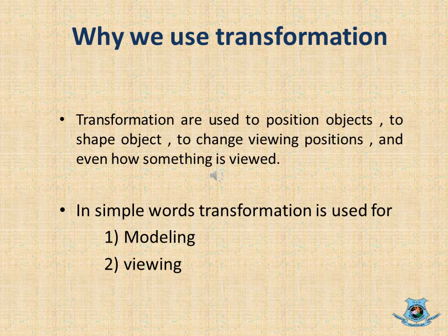Then, first is the perspective projection. In perspective projection, the distance of the projection plane from the center of projection is finite. The object size changes in inverse order with distance. The perspective projection is used to determine the projector lines that come together at a single point.